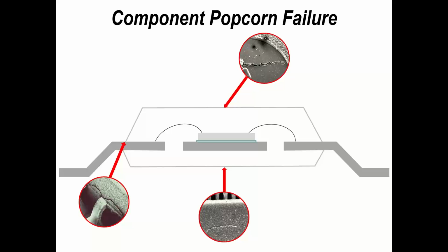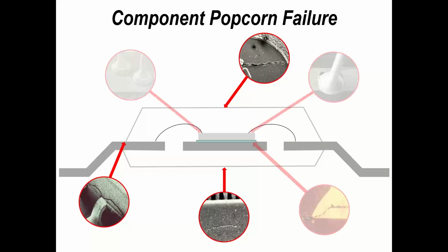It is generally unusual to see it on the bottom. I've tended to see more cracking on the tops of packages. But then again, if you had a problem which didn't actually cause a fault at that time, if it was on the bottom, you would never know. So sometimes my perception might be incorrect because we're not actually looking at the package at the bottom all the time. But if you do failure analysis, then you would be able to detect where the actual cracking was on the package. So that's an example.